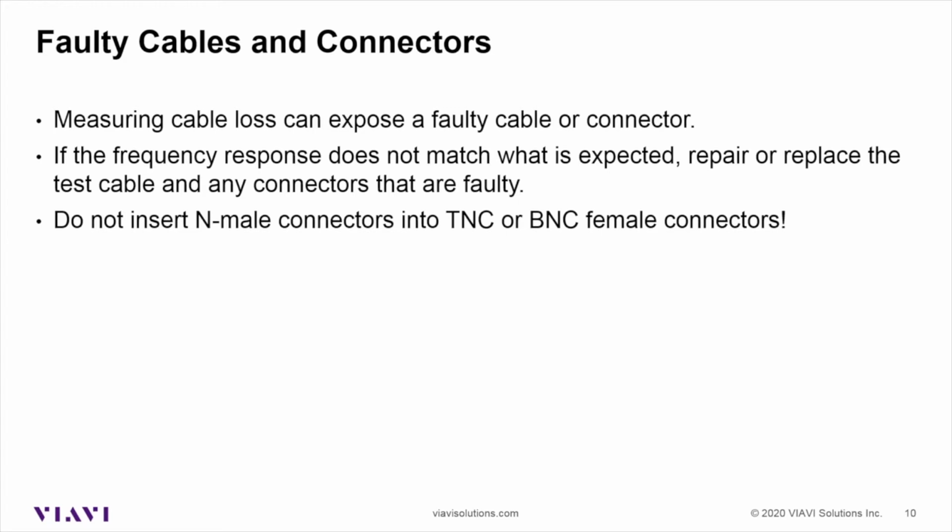The problem with that is that the N connector has a larger center pin, and what happens to the female BNC connector, and again, I have TNC in there too because we do use TNCs on the 3920B, is the fingers on that socket get splayed out, and then they no longer make contact when you put a BNC or TNC connector in there.